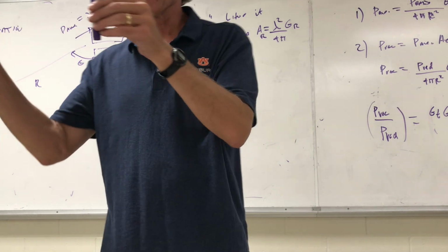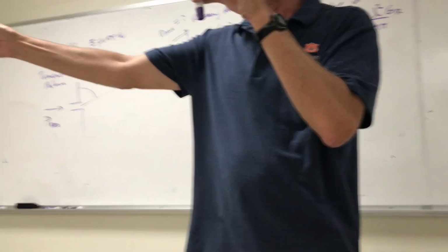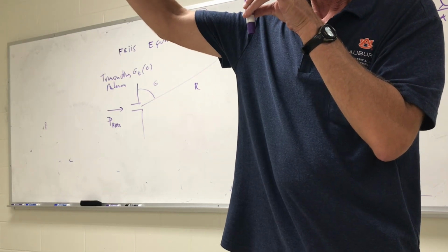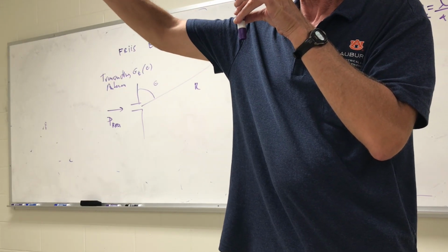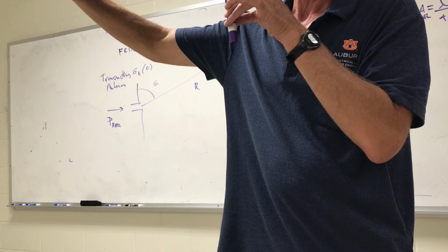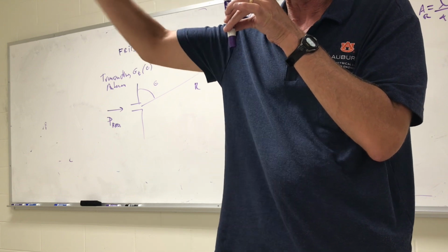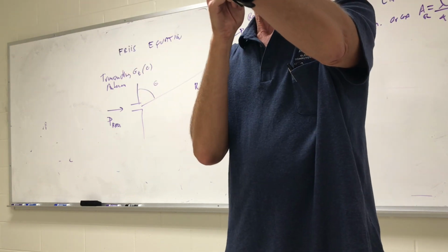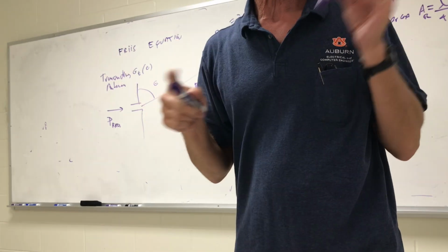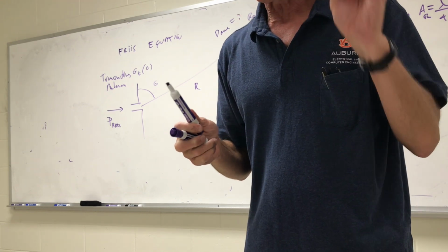And there's a couple things. If you're looking at this and I'm moving the second antenna this way, but it's not tilting, it's just staying aligned like this, then what will affect the gain is how it moves in the plane of the board, if you can think of that. That will change the actual gain of the receiver. If it's aligned like this and it's up this way, but it starts tilting this way, then you multiply by a cosine of the tilt angle squared. You with me? Just things you need to consider.